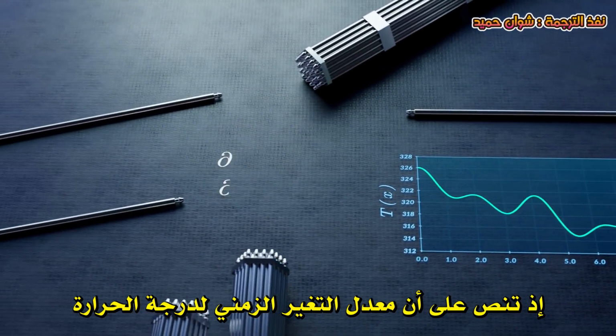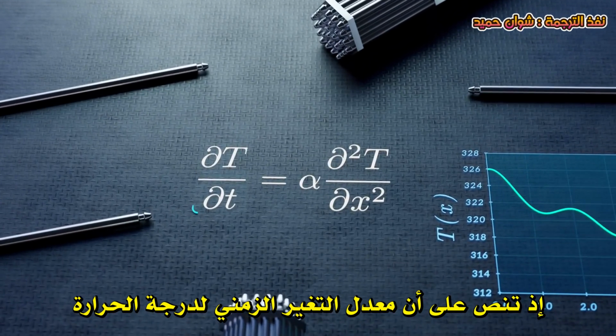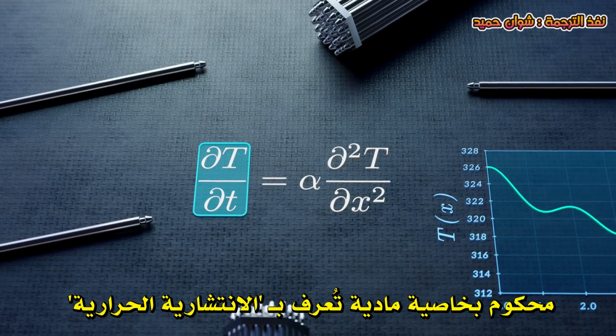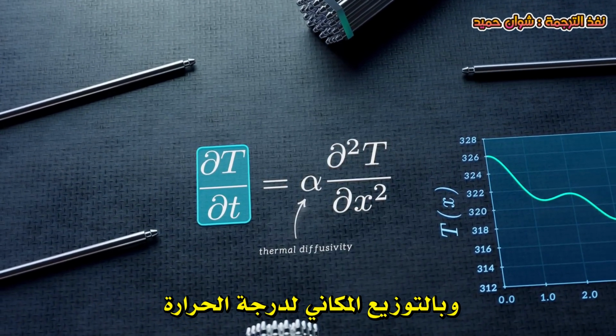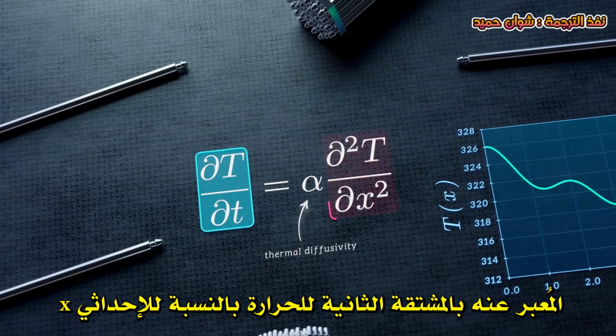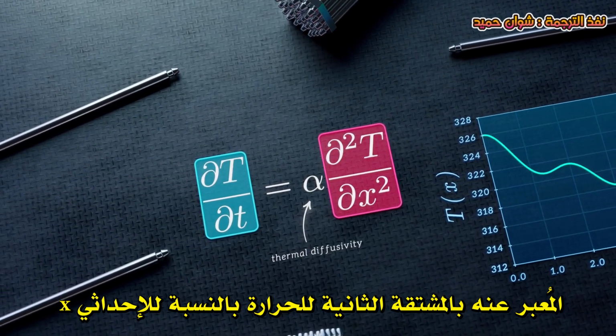It tells us that the rate at which temperature changes over time depends on a material property called thermal diffusivity, and how temperature is distributed along the rod, represented by the second derivative of temperature with respect to the position x.